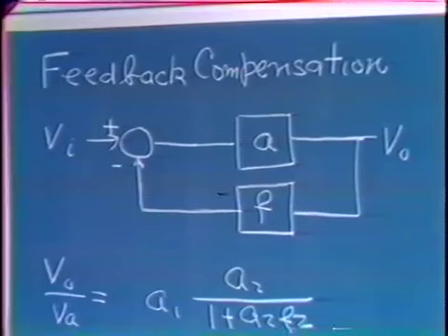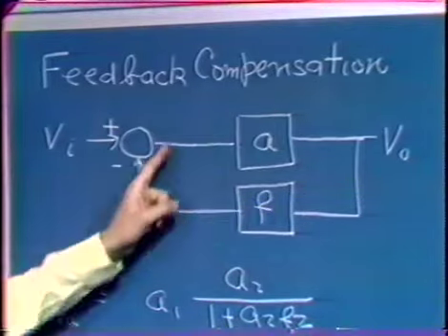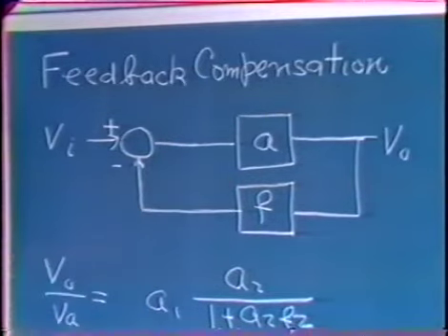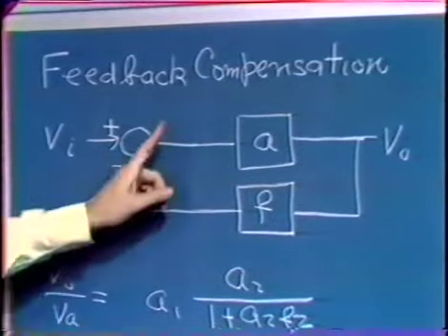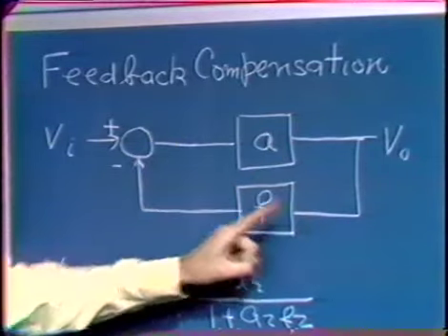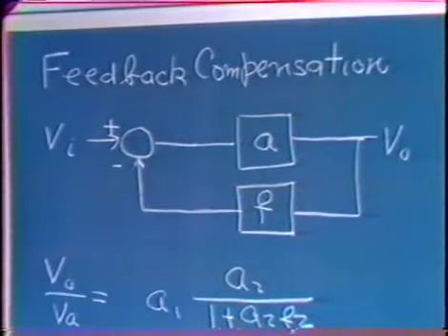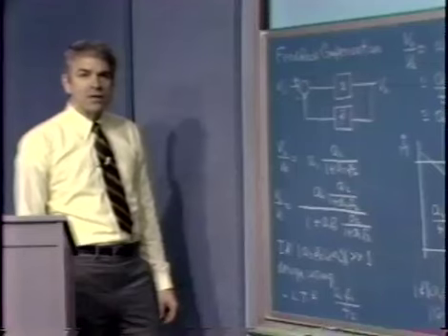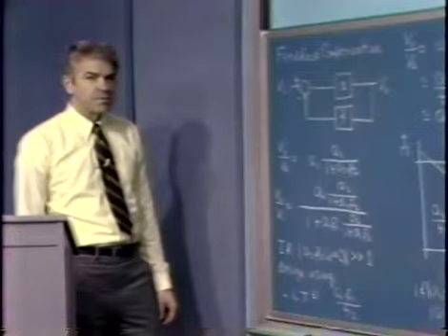To implement the series compensation or cascade compensation that we've been considering up till now, we add one more, or possibly more than one, element somewhere in the loop. We add it in series or in cascade with the fixed elements. We could add it here, here, here, here. The effect of adding it in any of those places on the loop transmission is identical, of course, and so it has the same effect on stability regardless of where we locate it. However, the actual closed-loop gain of the system varies as a function of where we locate the series compensating element.